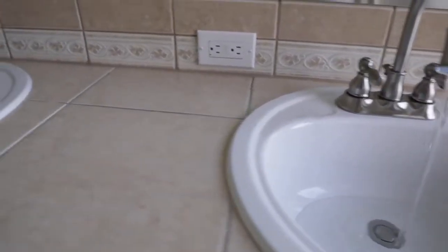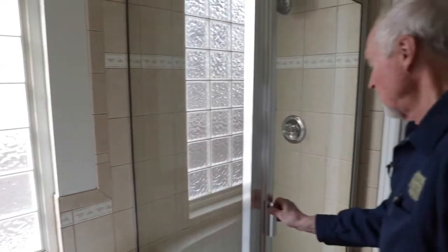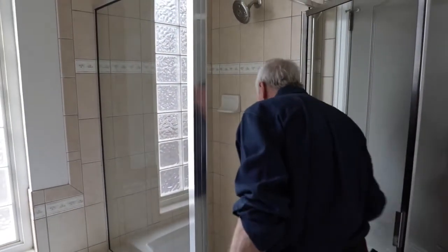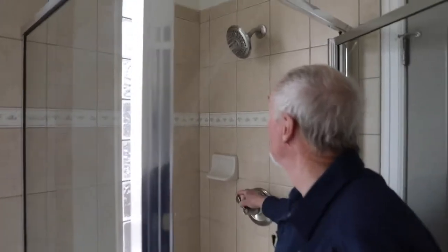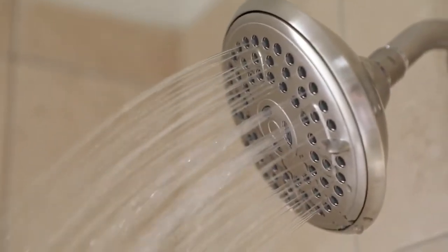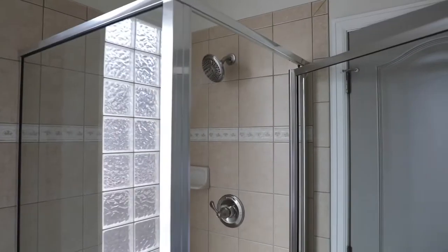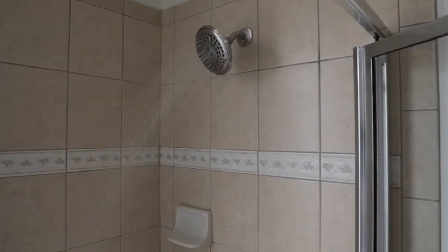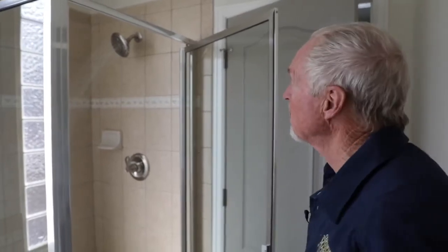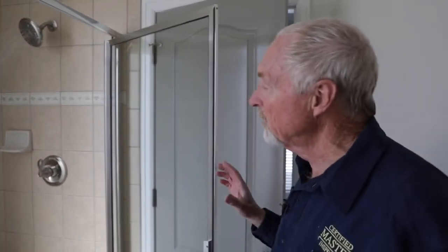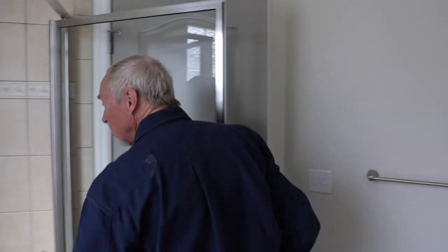Also, I'm going to turn my tub back on quickly here and run my shower and see if I get a decent flow of water on my shower. I have a little loss of flow there. I'm going to turn this off. We'll see how much it improves if I turn these off. Not a big difference. I don't have a concern here because even though that's not exactly a hard shower and may have clients say something about it, it's not an issue with too many fixtures running. It's just an issue with the individual shower head here going on.